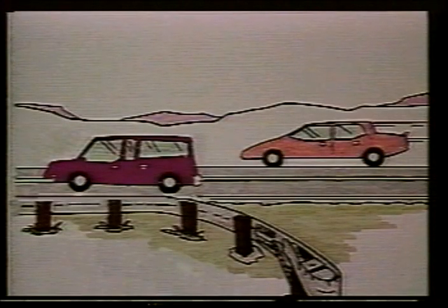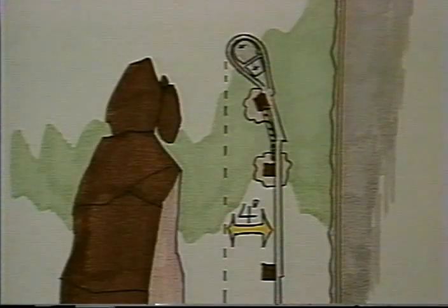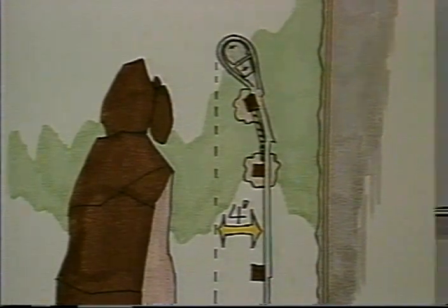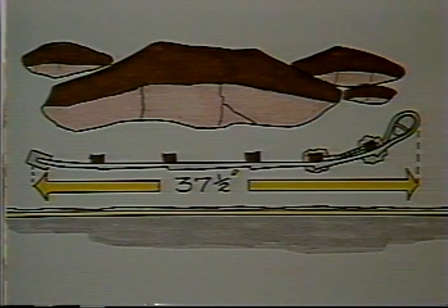Flare characteristics of the BCT are critical to its proper performance, particularly with the smaller vehicles that might impact the system. Head-on hits with unflared roadside barriers can cause severe damage to these smaller cars. Flare for the BCT must be parabolic with a 4-foot offset from the tangent section of the railing. Length of the BCT is also a critical factor in its reducing injuries and deaths when hit. Recommended length is 37.5 feet.